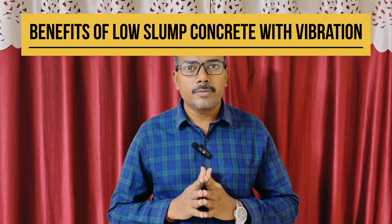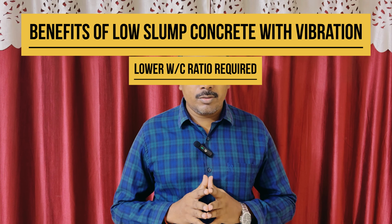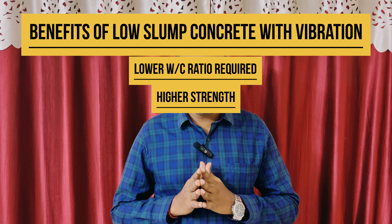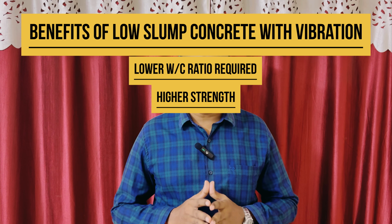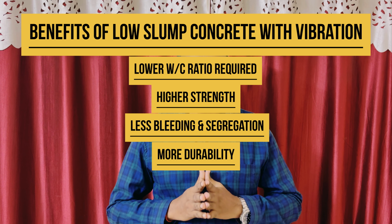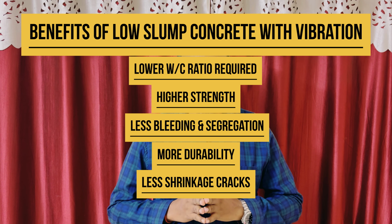Now let me tell you the benefits of low slump concrete with vibration. Lower water cement ratio, which clearly means higher strength. We have already discussed this point in our water cement ratio video. Less bleeding and segregation, better durability and fewer shrinkage cracks. That's why mass concrete, pavements and foundations often use low slump plus vibration. So now we know the benefits of low slump plus vibration.